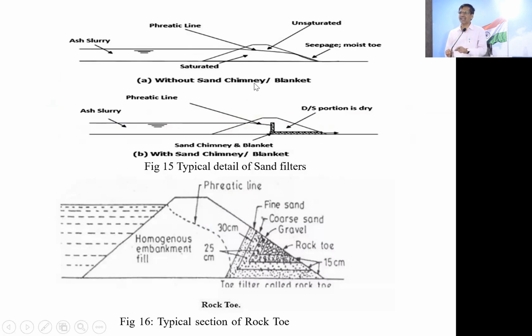Because for slope stability analysis, mostly now the software is doing it. You have to simply put in the inputs. But the more difficult part is what the input should be, how to interpret that input, and where I should get the input. That is more important, not doing the analysis. Because I'll show you, whether limit equilibrium or Plaxis, I have to deal with both. The values are almost similar. Factor of safety you can also get through Plaxis. Plaxis will give you extra settlement and so on, but you can get both.